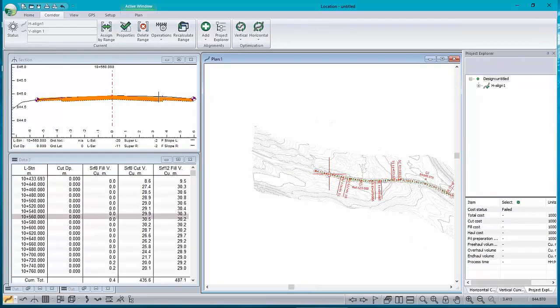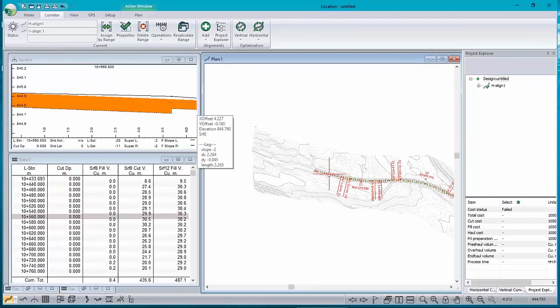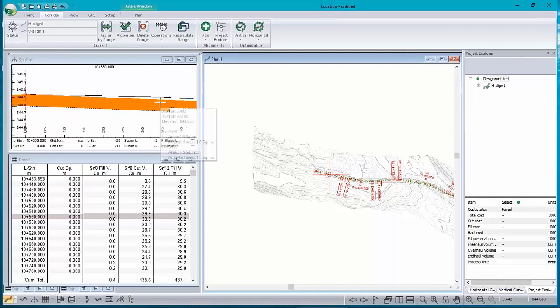Oh, and here's a bad one. This is what Lee was talking about earlier. This is the situation where the designed pavement is below the existing pavement, so the effective milling depth becomes deeper than the prescribed milling depth, which is probably going to leave the pavement underneath too thin, and it may even remove it entirely. So bad news here. What should I do?